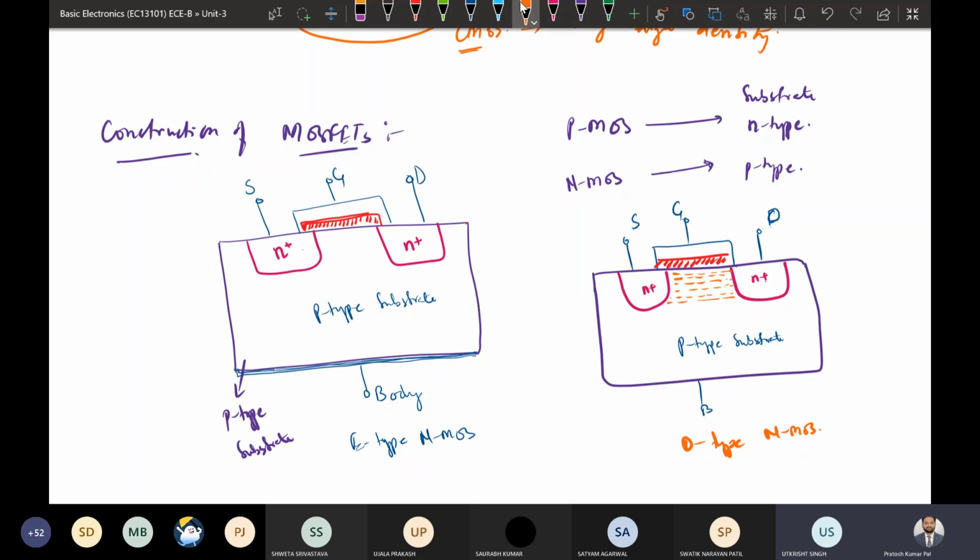We will be making sure by using the doping that we provide more electrons here, similar to n plus region. So n plus region is having majority electrons. Here also electrons are there. So whatever gate, suppose gate is 0, then the maximum current will be flowing. So as we are going to apply the gate, that is VGS less than 0, that means we are going to apply negative here. So as we are going to apply negative here, the positive will be attracted in the channel region.